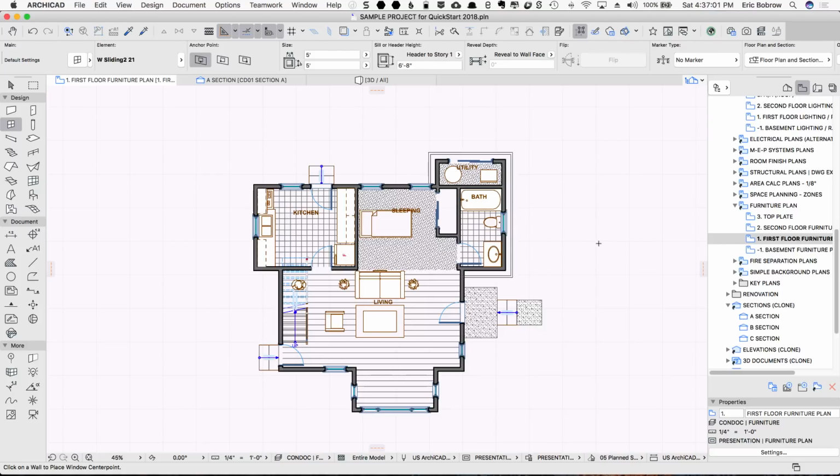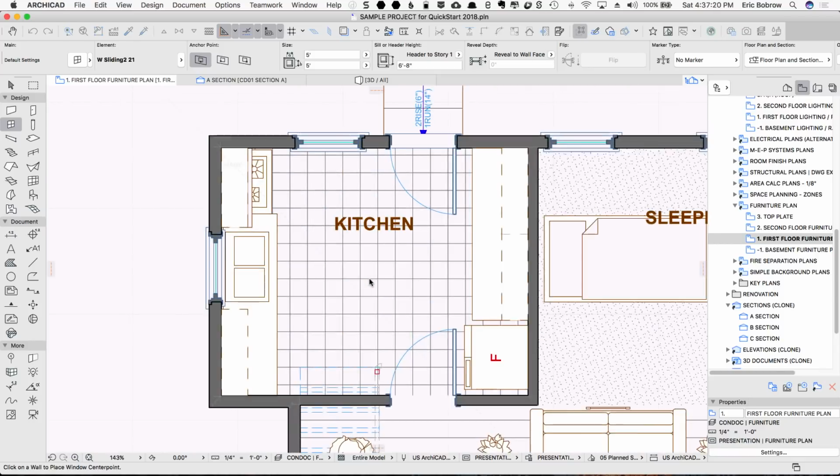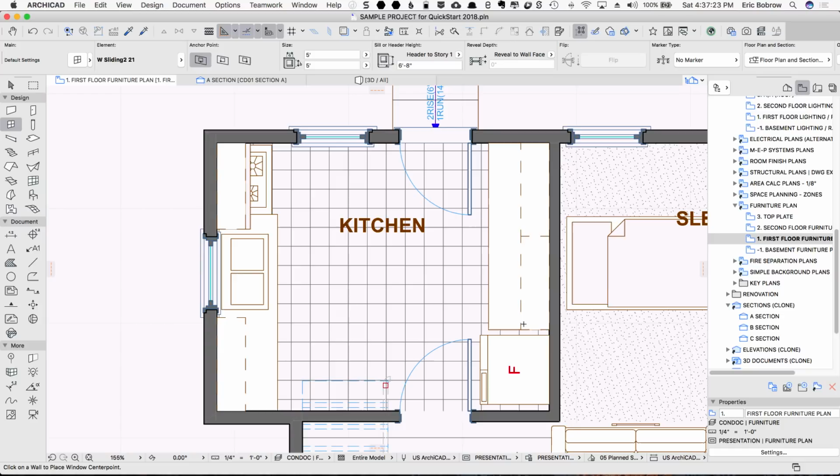Now let's look a little bit at how you navigate within a view. If I want to zoom in on a view, I can do it in either of two ways. I can use the little magnifying glass, increase zoom, and then click, for example, at one corner and then just go to another corner, and that's going to indicate that I'd like to zoom in on this area.